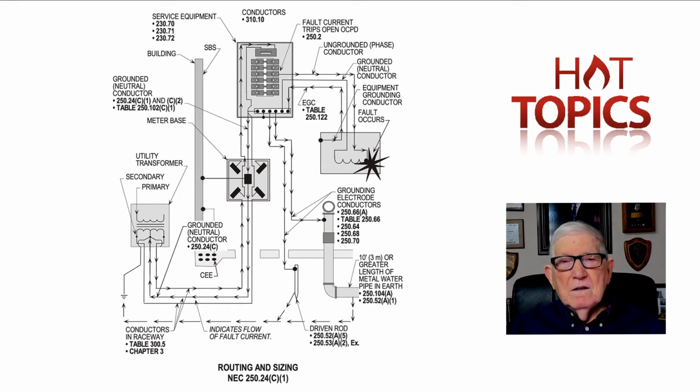The maintenance people were pulling in a branch circuit and used a metal fish tape and got it into the bus bar and metal enclosure, created a ground fault, but I didn't size that in those days by my table 250.94, and it was too small.